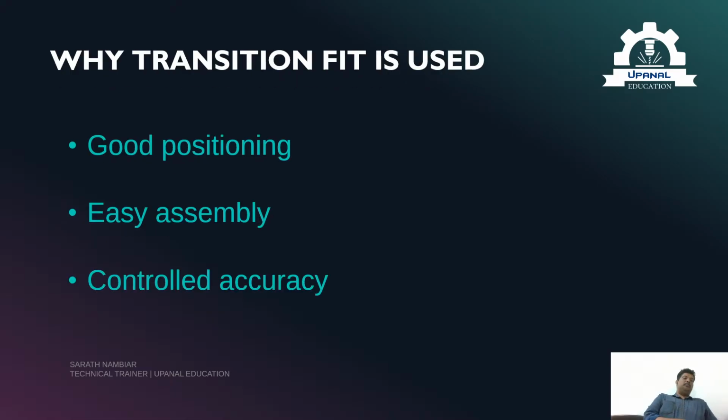Transition fit gives balance between the clearance fit and the interference fit. It provides better accuracy than clearance fit, and easier assembly than interference fit, so engineers use transition fit when position accuracy matters, but disassembly may be required later. You can think of it as a firm but friendly fit. Not too loose, not too tight.